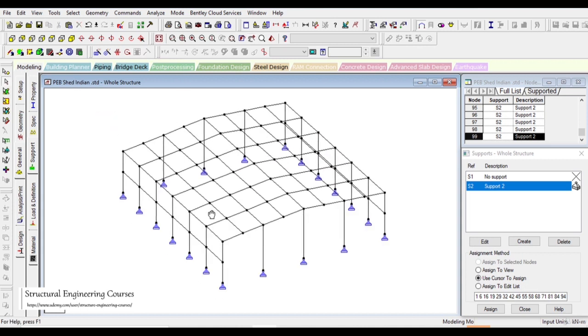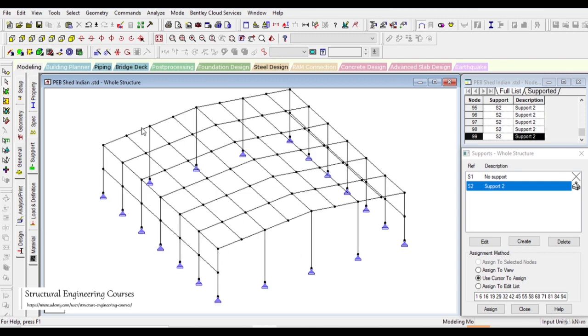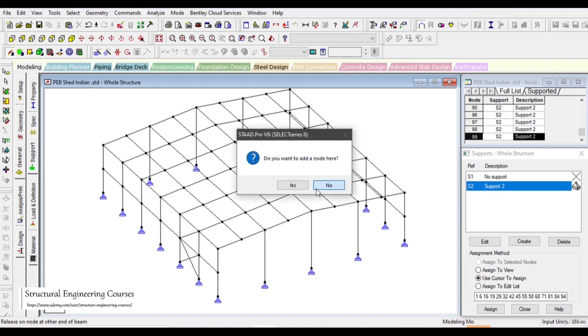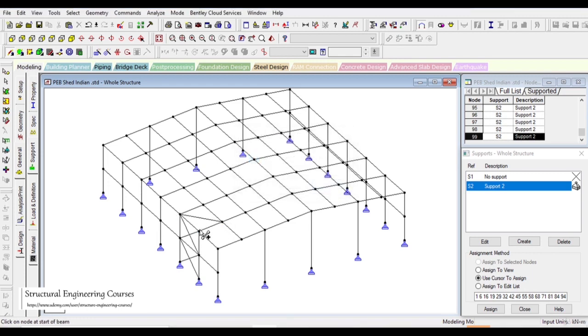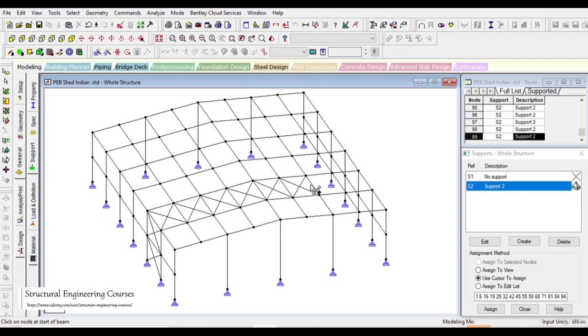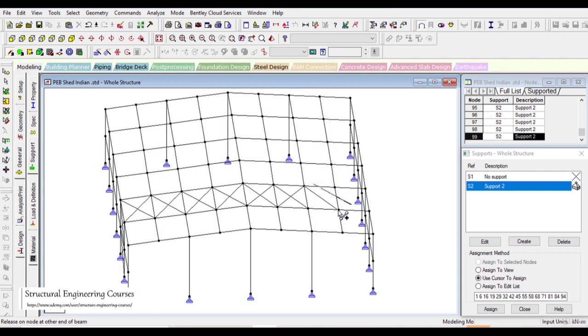So to brace the structure along the perpendicular direction, what we need to do is that in addition to the ties that we shall provide, we shall also provide additional bracings also. So this bracing is also a very important concept. Some of you must be thinking where and how this bracing should be provided. So as a thumb rule that you should know, bracings are always provided along the weaker axis. There is no logic in providing the bracing along the stronger axis.